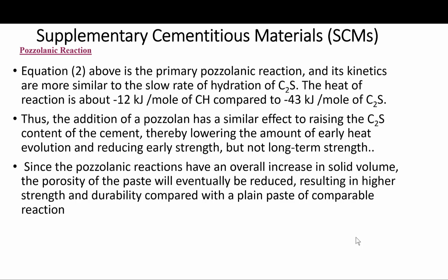So since pozzolanic reactions have an overall increase in solid volume, the porosity of the paste will eventually be reduced, resulting in a higher strength and durability compared with a plain paste of comparable reaction. So that is really the major benefit we get from the use of the SCMs or the pozzolanic materials in this context.